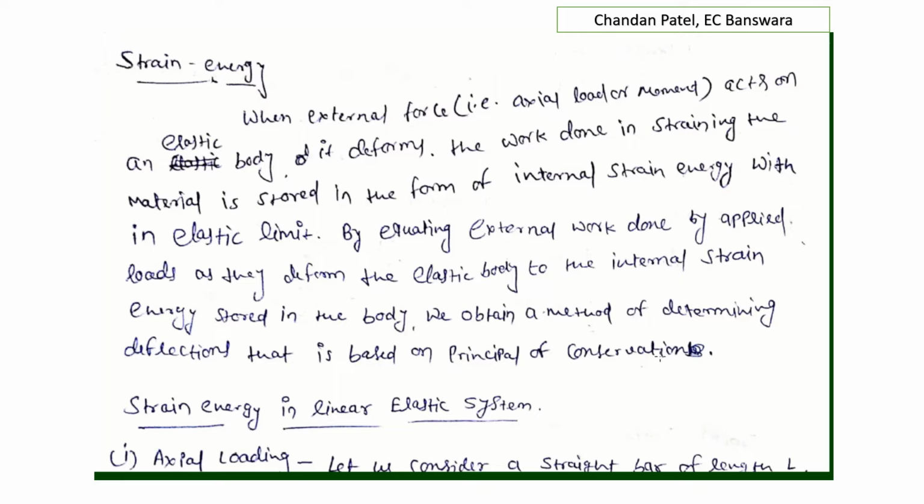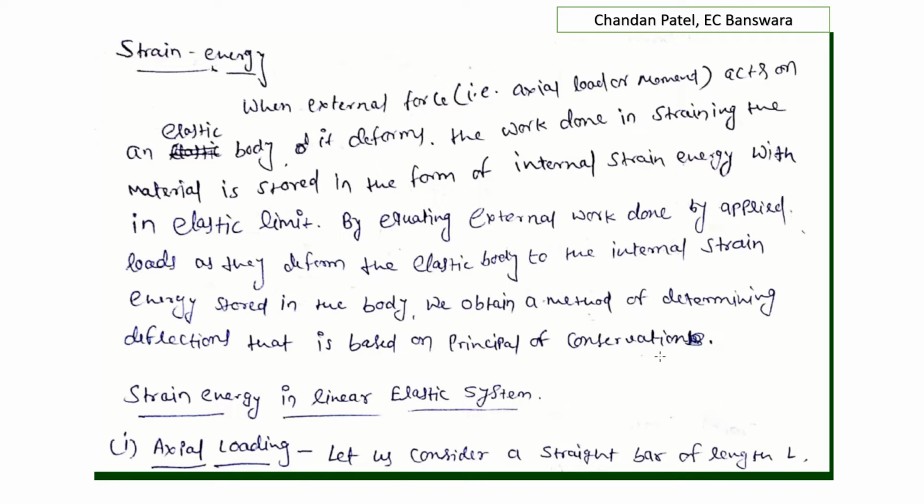Suppose there is a pin jointed structure. When the members are in tension or compression, the energy stored depends on the direct force only. However, in beams and frames having rigid joints, shear stress and bending stress may also occur at any section, and the total strain energy stored depends on the magnitude of direct force, shear, and moment. While analyzing statically indeterminate structures, the work done by direct and shear force is neglected as compared to the bending.